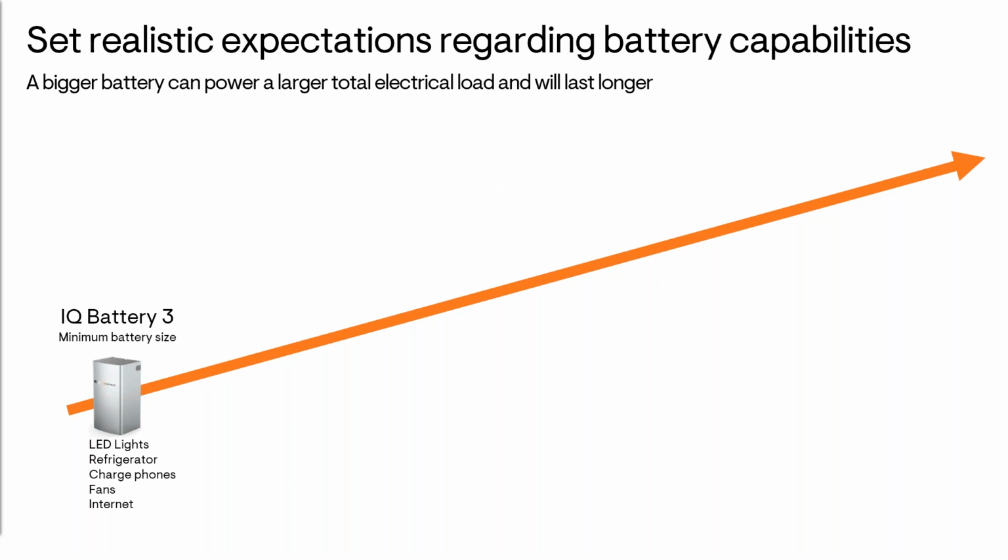While the Enphase IQ batteries start at just 3.3 kilowatt hours, this is a pretty small battery for most homeowners. If the homeowner wants this small battery, you should be clear that they should limit the number of loads they're trying to power and probably also use Enphase load control in order to shed loads that could potentially overload a small battery.